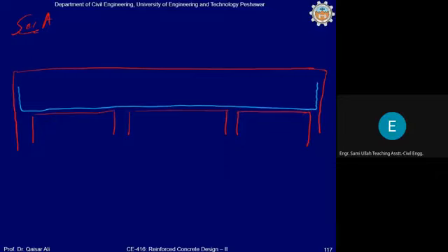And this reinforcement will be given closer to the bottom face, as you know. This is number 4 at 6 inch center to center. Similarly, the bottom reinforcement along the longer direction will be denoted by these dots.